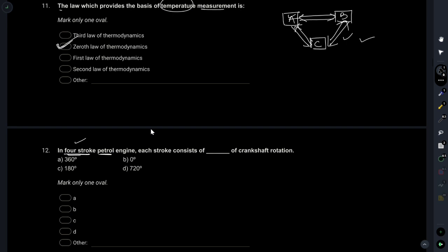If I show the arrangement, let this be the cylinder, and let this be the piston, which is now placed at the top dead center, and it may move from top dead center to the bottom dead center as well. So this is the bottom dead center. This piston will be connected with a connecting rod, shown at the vertical position at this instant, and the connecting rod is connected to the piston at the gudgeon pin, right? Do remember it. The connecting rod, which is this one, is connected to this piston at this particular pin, which is known as your gudgeon pin.